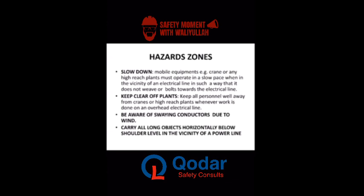We also need to have a slow down zone where mobile equipment stays or is stationed. We would not want to work so fast or operate these plants so fast. We also want to keep clear of these plants, knowing that only qualified personnel should be there. We also want to be careful of swinging wires due to wind and all that. And when carrying objects, we want to carry them horizontally below shoulder level when walking under this power line.